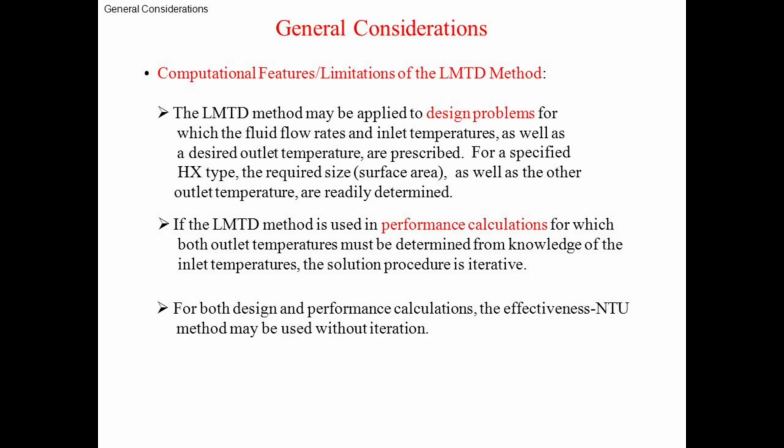The LMTD method may be applied to design problems for which the fluid flow rates and inlet temperatures as well as the desired outlet temperature are prescribed. If the LMTD method is used in performance calculation, for which both outlet temperatures must be determined from the knowledge of the inlet temperatures, the solution procedure is iterative.